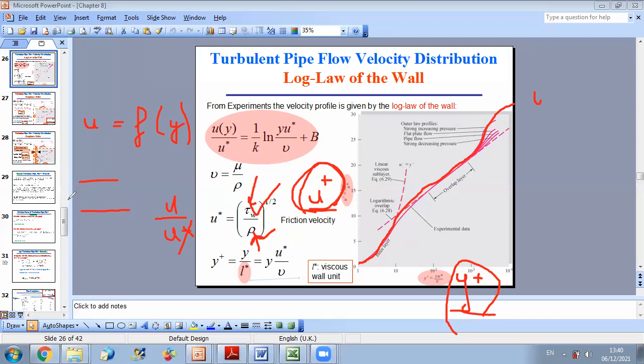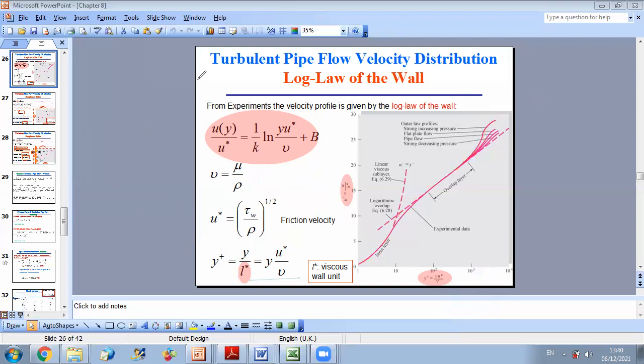If you have the same groups in the model and prototype, you can extrapolate your results. So if this result is based on turbulent flow in a circular duct, then you can use it for any turbulent flow in a circular duct. You just should compute your dimensionless numbers.